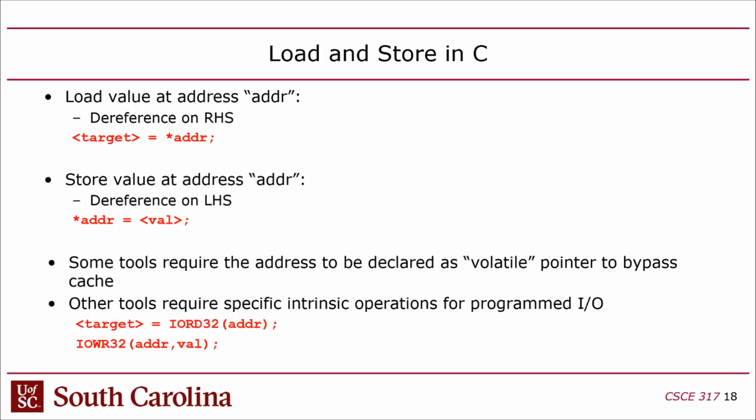Now you have to be careful with that, though. Normally, if you're doing programmed I/O, you're probably going to want to use an intrinsic to make sure that you get the proper load and store. This is why we use this in Altera, because if you don't and you just use this approach, you might get caught by the cache. You're going to set the LED to turn the LED on, but instead of going to the LED, it just gets captured in the cache, right?